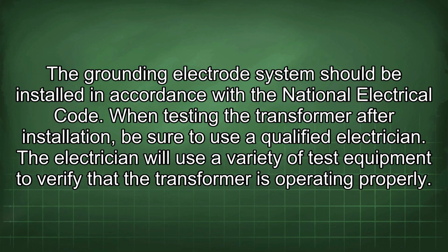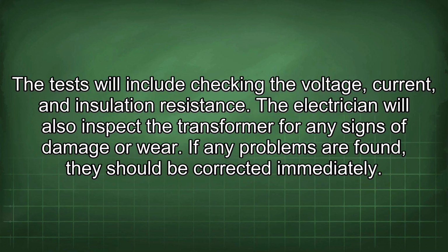When testing the transformer after installation, be sure to use a qualified electrician. The electrician will use a variety of test equipment to verify that the transformer is operating properly. The tests will include checking the voltage, current, and insulation resistance. The electrician will also inspect the transformer for any signs of damage or wear. If any problems are found, they should be corrected immediately.